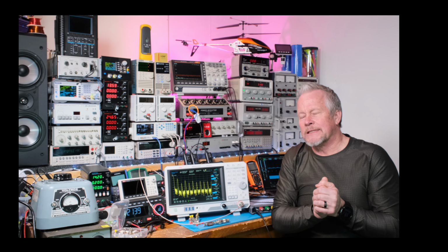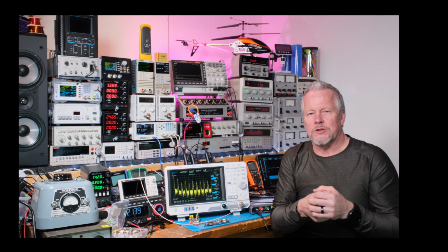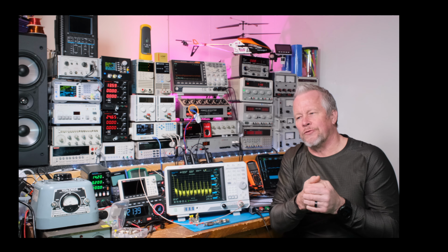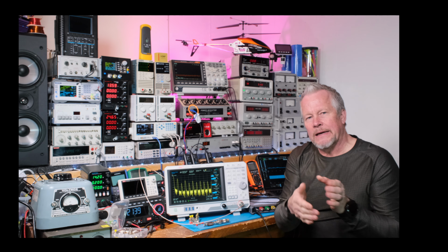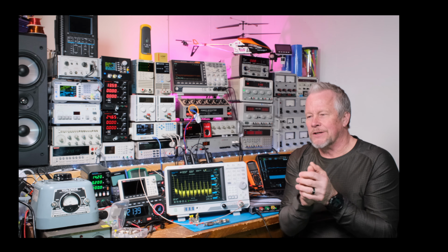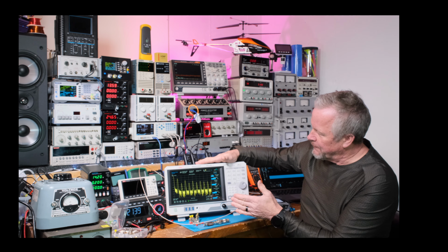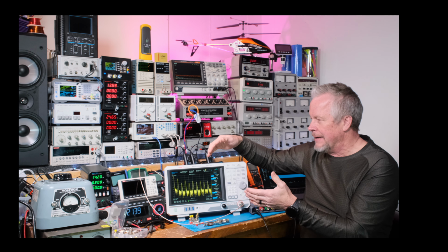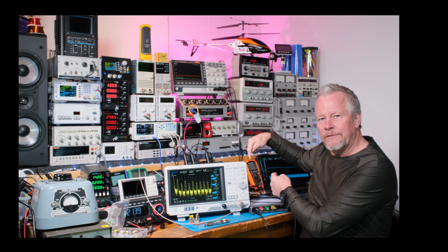You can see things like artifacts of other things, like if you've got a FET that's ringing or something, you can see that 10 megahertz overshoot ringing. And on this thing, besides the harmonics from the 10 meg, I could also see little peaks in between, and that's coming from that ringing. So I could look at that frequency and find it on the spectrum as well. So that's the difference between, hopefully the Pico made it a little bit easier, and maybe it also was helpful to see the difference between a spectrum and a scope and an FFT.